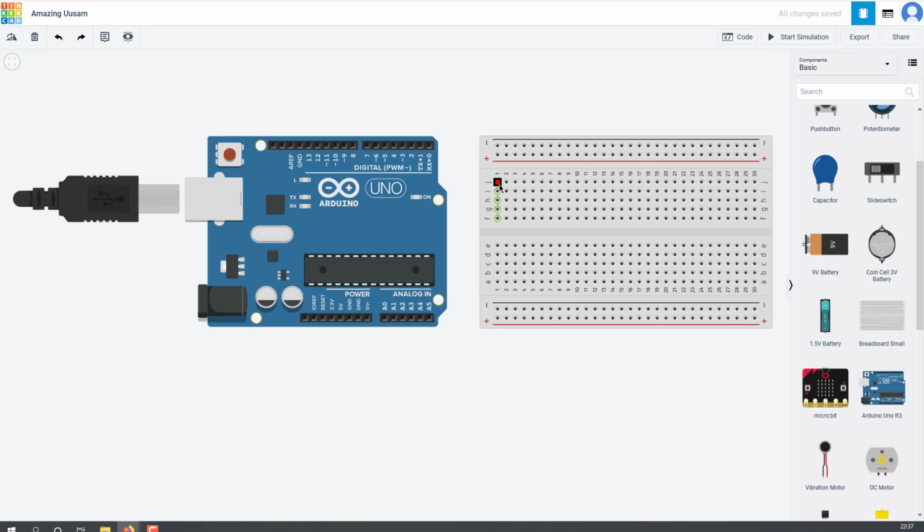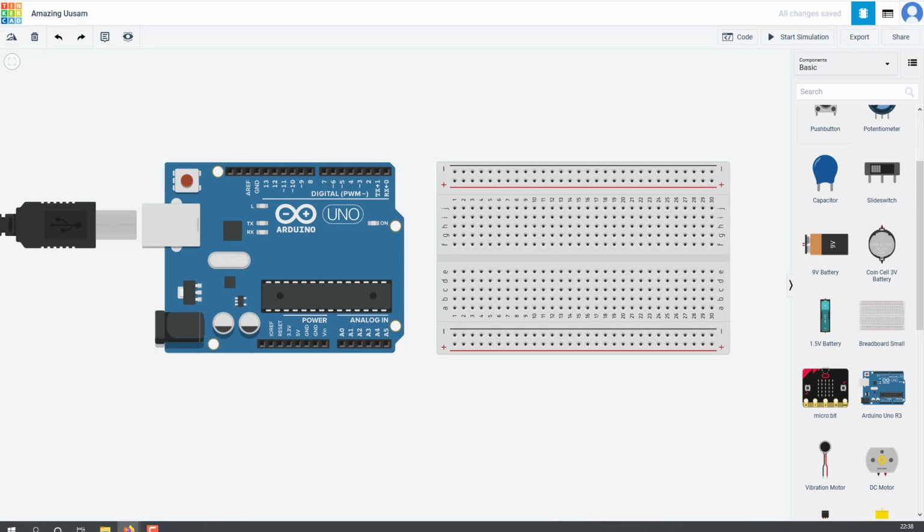Just to explain how the breadboard works, these columns are one. So if you see F to J is one. At the back of this breadboard, you have a strip of metal sitting, and so this will be one complete circuit. The positive and negative are arranged in a row instead of columns, so this is all one line. If you plug something here or here, they are all one single line.